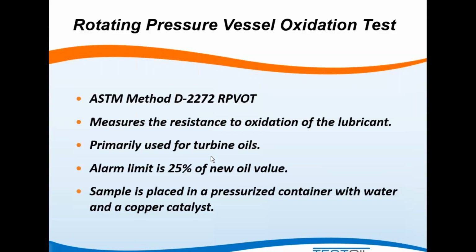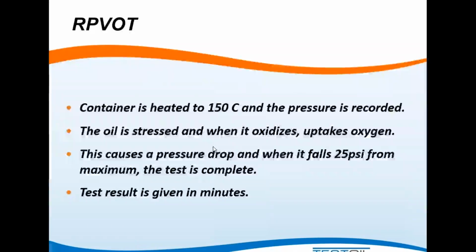Now, I've seen samples that may not have a fantastic RPVOT, but in service they do well. I've seen other oils that score very high on RPVOT, and in service they have varnish issues. So really, you want to stay within the lubricant. You want to compare your new with your used. You don't really want to compare one lubricant to the other. It's not really meant to be that way.